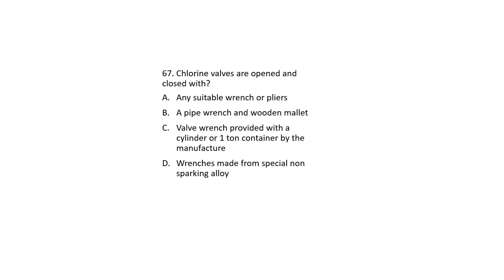Chlorine valves are open and closed with any suitable wrench or pliers, pipe wrench and wooden mallet, or a valve wrench provided with a cylinder or 1-ton container by the manufacturer, which is made from special non-sparking alloy. Answer is going to be C. And with chlorine, they're talking about chlorine gas.